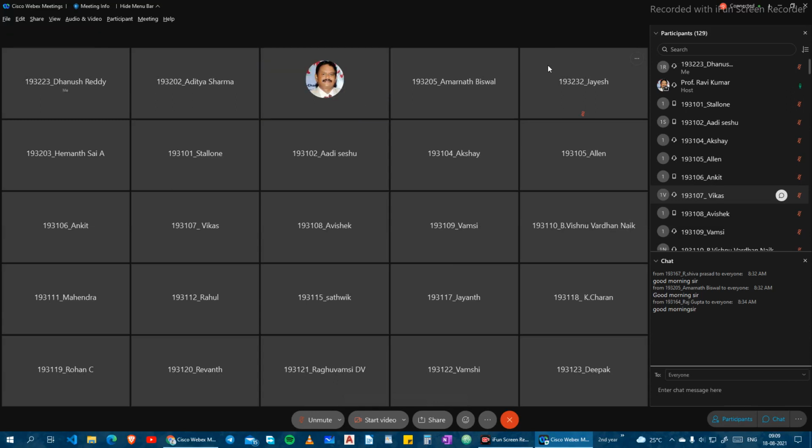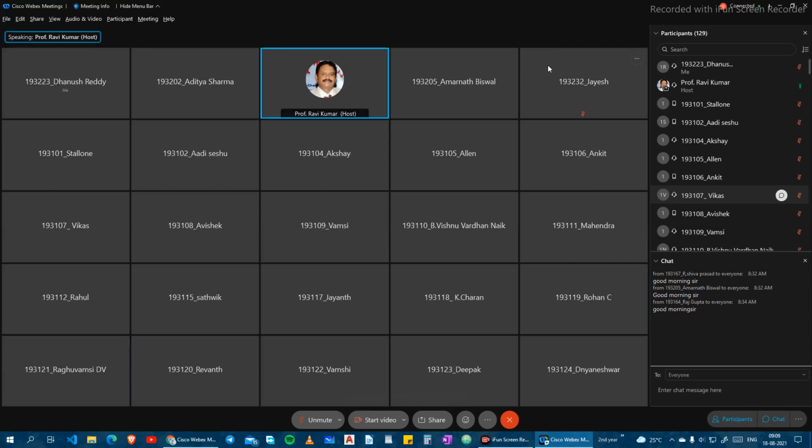Sir, out of the three scavenging systems, which is the more efficient one? Uniflow scavenging will be adopted for the multi-cylinder two-stroke engines, particularly in marine boats and all. But cross flow will be used for two-stroke engines, with modification of the piston crown and all. Loop, most probably racer engines are going to use a loop system, because more space is required for the designing concept.